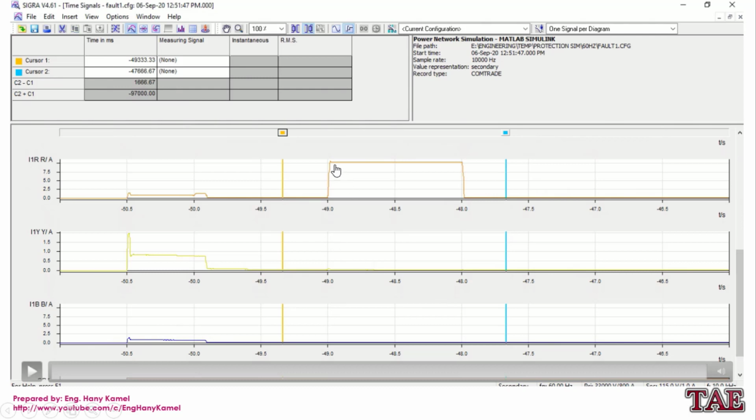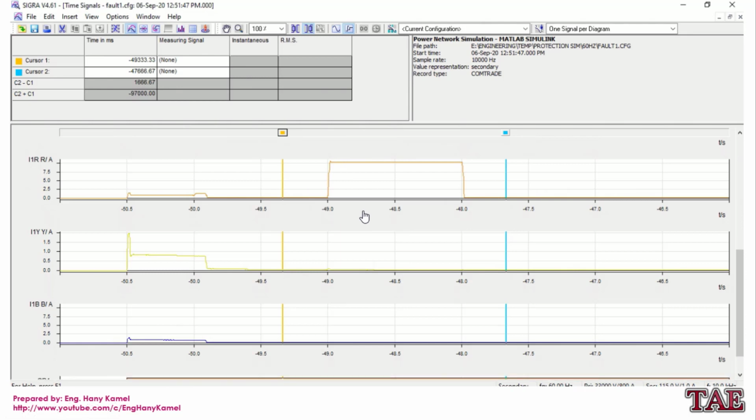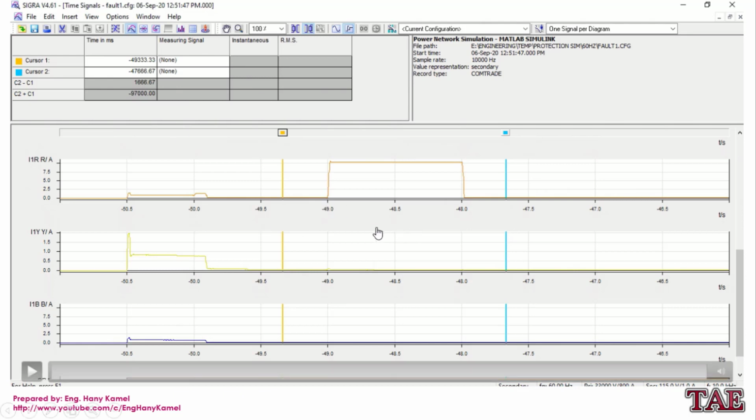And now the fault current in our system, substation 2, which happened directly in the substation, was a higher current, so it tripped directly. But as I said, I made it 1 second so we can test our protection relay to check its complete behavior, whatever the time delay we got.